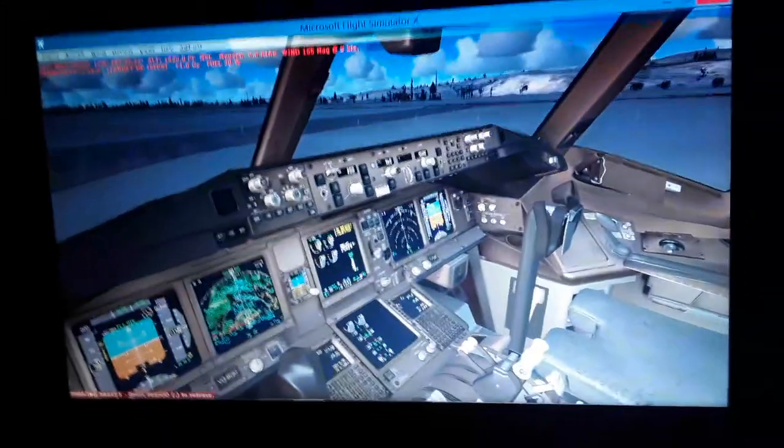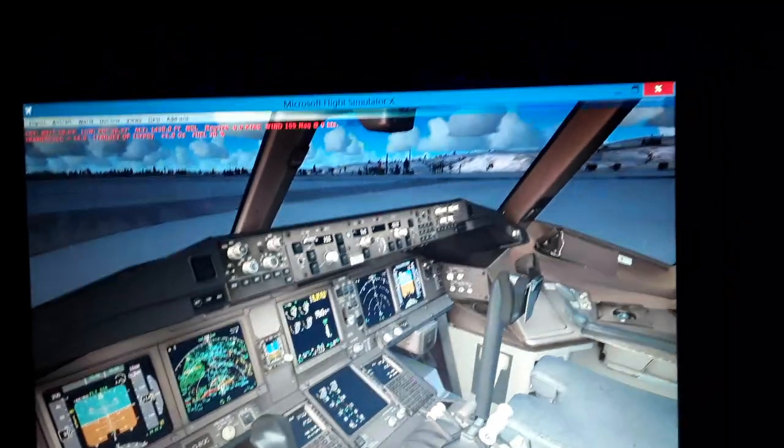So we have also the navigation display that displays the GPS position, the inertial reference position of the aircraft, the magnetic heading and track, the magnetic north pole and true north pole, and the magnetic variation depending on where we are in the world. You can also see the terrain and weather reflections from the weather radar. You can see the terrain elevation in red, yellow, green and blue also, the lakes and the sea. We can see also other aircraft that fly around our own aircraft.